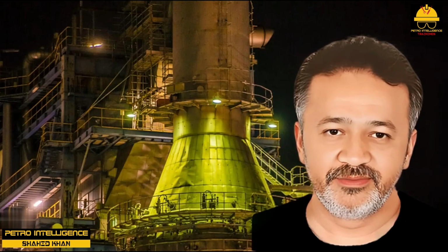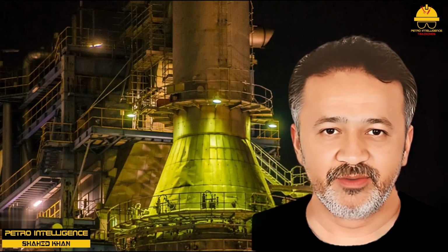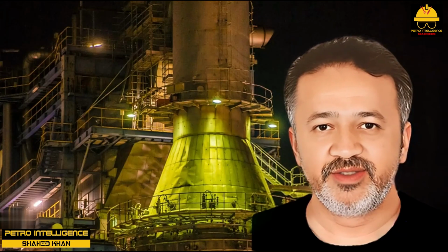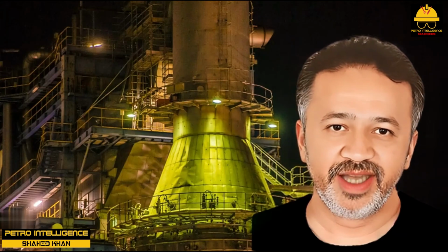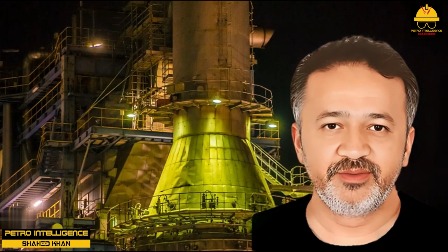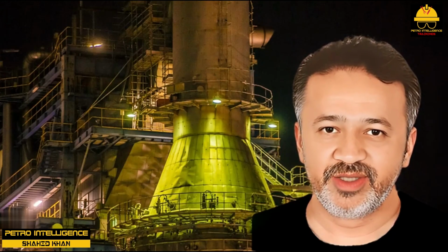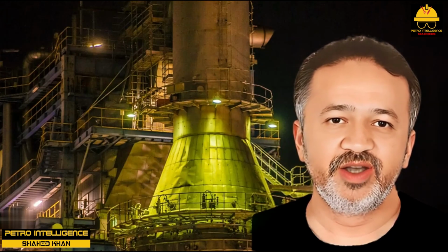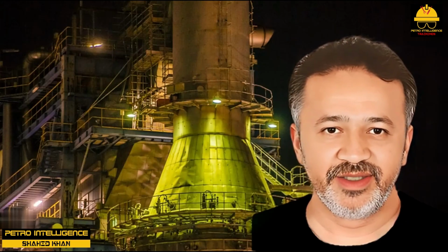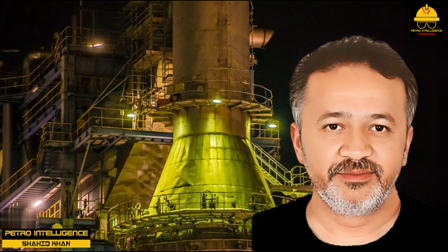Here is what happened. Preheating the air by 300 degrees Fahrenheit had raised the burner flame temperature by 300 degrees Fahrenheit. The hotter flames then radiated more heat per pound of fuel consumed, and as a result, the firebox became much hotter. The same factor that reduces fuel consumption in the radiant section also reduced the flow of flue gas to the convective section, thus reducing the convective section outlet temperature.